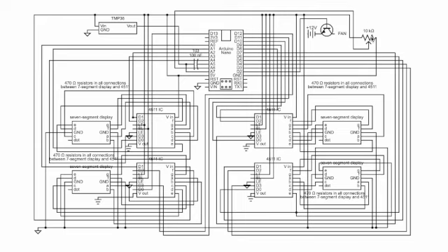Essentially, if the potentiometer's voltage is smaller than the TMP36 voltage, or another way of saying it, the temperature that the user inputted is smaller than the temperature the TMP36 is giving, then this fan would turn on. On the contrary, if the temperature set by the user is greater than the TMP36 temperature, then the fan right here would not turn on.